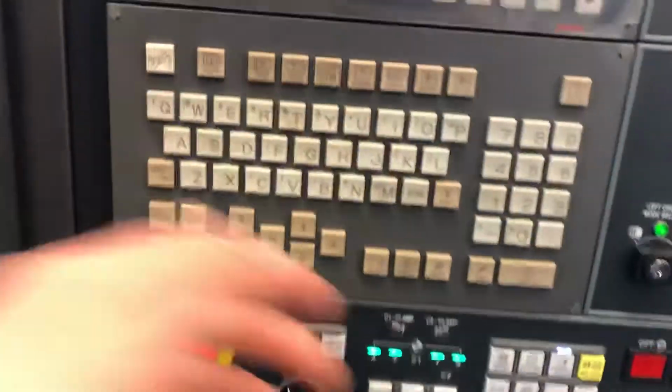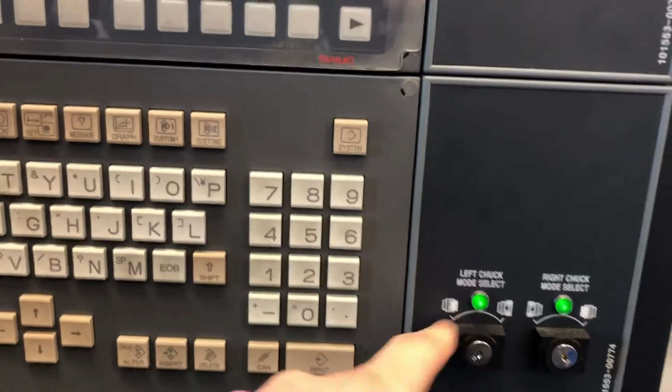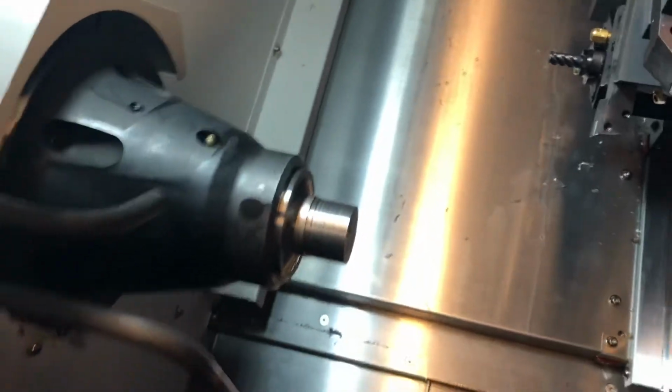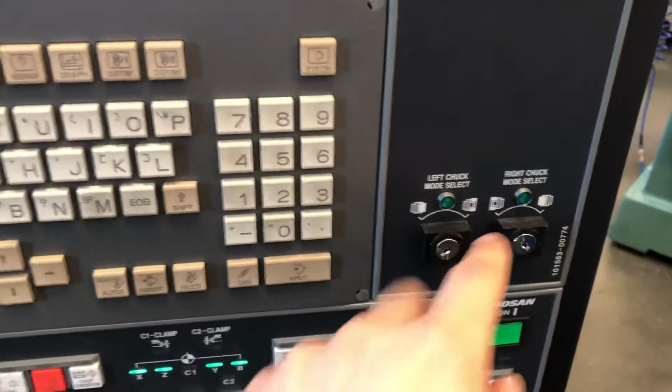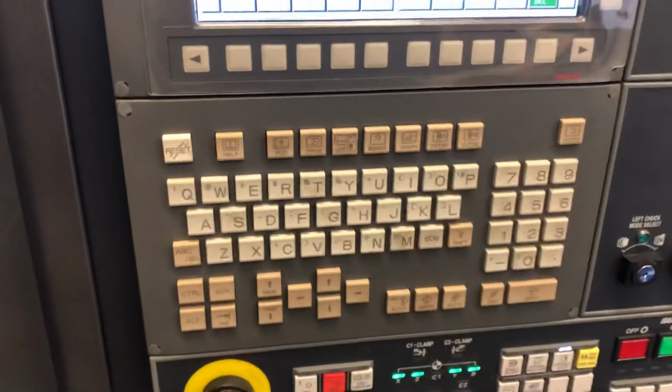Other than that, over here, these lights will be lit up if your chucks are properly closed on something. So both of these green lights are on. If we take a look in the machine, I have a part in this spindle and in this spindle. If I go ahead and unclamp the left spindle, you can notice that the light turns off. I can do the same for the sub spindle with the foot pedal down there. Now both lights are off, and you can't turn the spindle on unless these two lights are on, or even run a program. So that's something to keep in mind. So that's kind of a basic button layout on this FANUC series control.